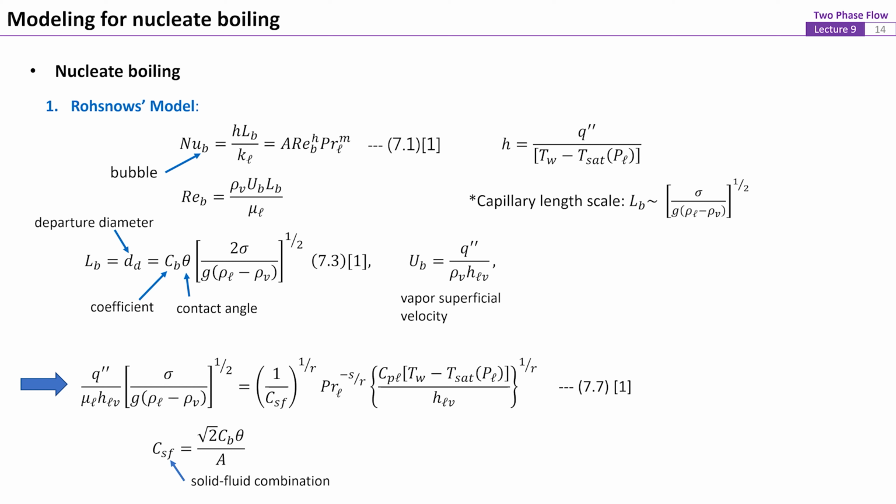In this model, it is postulated that the heat flow from the surface to the adjacent fluid is firstly treated as single-phase convection. The agitation of the liquid flow behind the wake of departing bubbles contributes to the increased heat flux. Therefore, the convective heat transfer coefficient, or the Nusselt number, is proposed to be a function of the Reynolds number and the Prandtl number, as in single-phase convection. This is shown by equation 1.